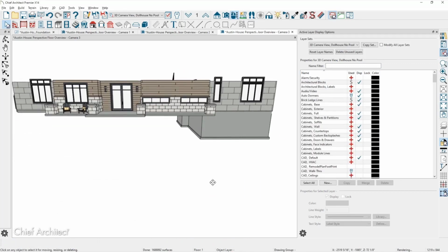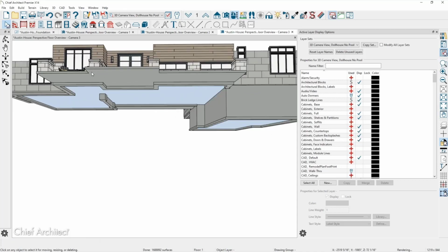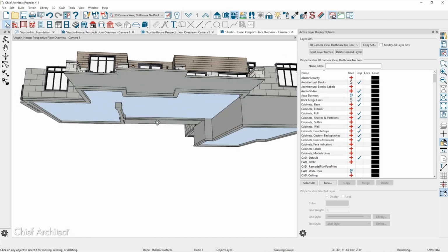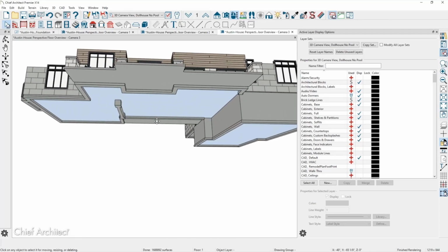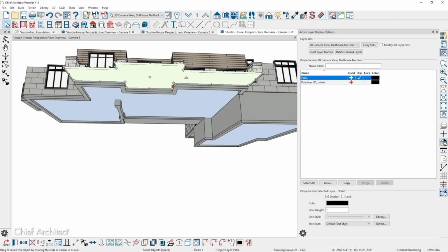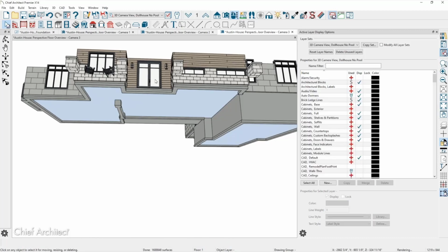And this actually has no structure, so you can see I just drew that as a separate slab. And then in my cross sections, I don't see that 36-inch peripheral beam because my roof supports with columns or something like that. It comes on that slab, and that slab needs to have those grade beams. So essentially that waffle slab extends to the edges of the slab that you have created. Okay, so I would need to remove this one that I drew, and your foundation needs to come out.